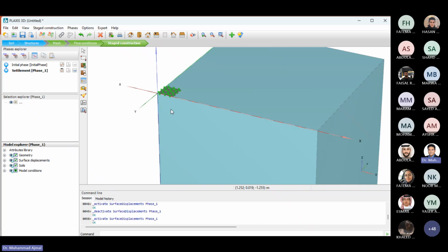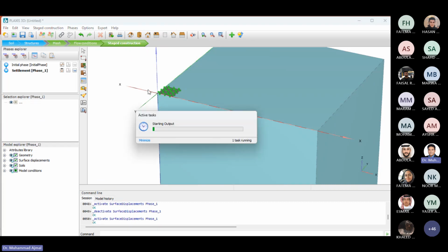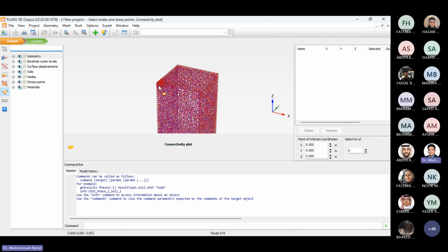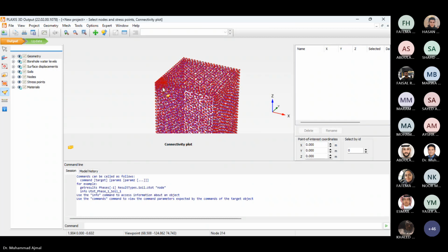But what is the important thing here? We need to record the data. When you apply this displacement, you need to get forces against some specific point, some specific location. So if you observe here, this is the point. The next option, the points with the triangle, indicates us to select a point for the curves. You need to record force versus displacement for that specific point. When you click on this, a new window will open and show us all types of nodes in our model.